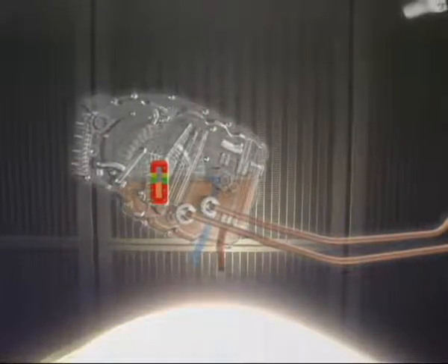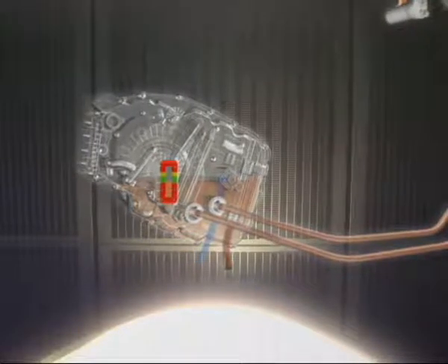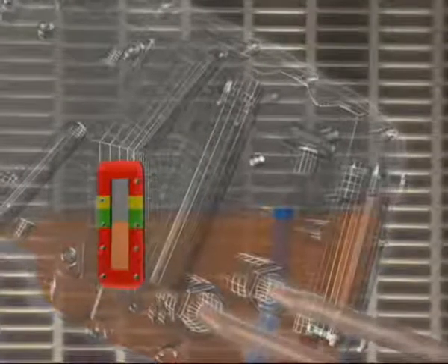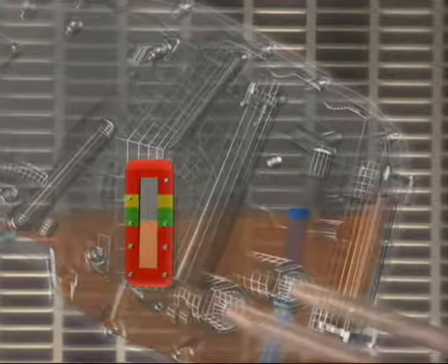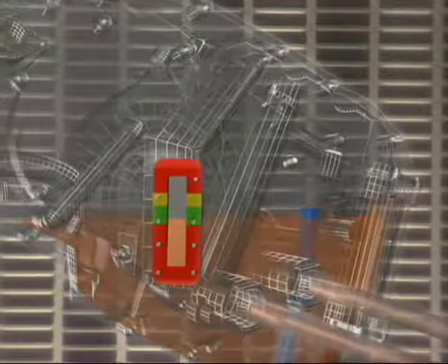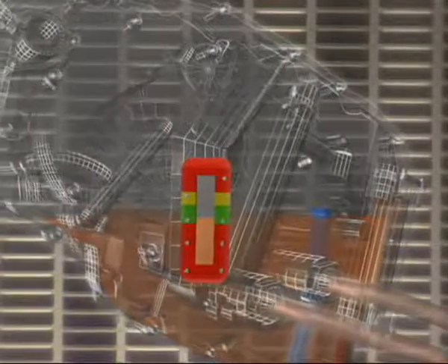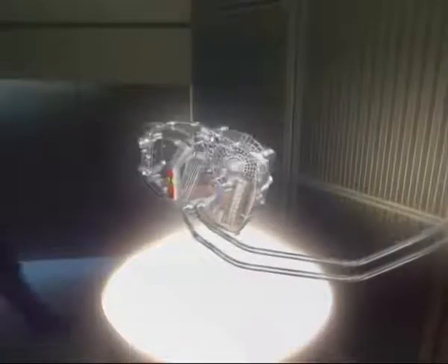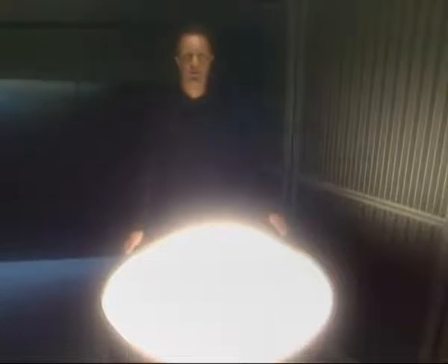On the A330 and A340, there is an oil level sensor. If the oil level is in the lower part of the green band, low oil level detection may be generated in operation, leading to additional burdens for the maintenance and flight crews. Now let's go back to the aircraft to service a genuine IDG.